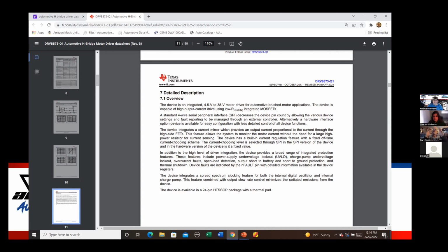Okay, so while these DTC charts have us focused on disconnect these two sensors and ohm the wires between here and here and this and that, and we're spending 3 hours testing down this trouble chart for this throttle motor code or this Valvetronic motor code, we're being fooled and run around the process the whole time, because what the manufacturer is not telling us is what happens next. Any kind of output short to battery or short to ground is also protected, and thermal shutdown is protected. Like Adam said, didn't Adam mention, a lot of times these things will happen because of heat, right?